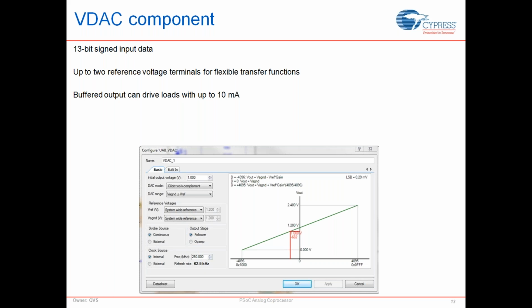So in such a case, you would use a strobe signal, which would be your update frequency. And when you use that, you don't have to be worried about when the update actually happens on the VDAC register. You could update the VDAC register at your leisure, but then the strobe would make sure that the updates happen at a consistent rate, and thus make sure that your filter is correctly designed to the DAC's update frequencies.